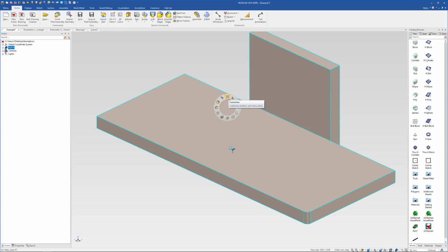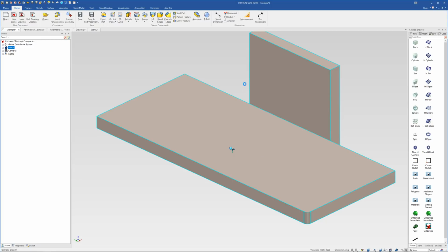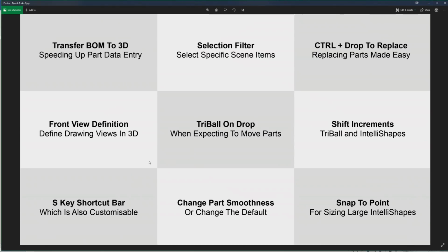When you activate it, this top button here will customize the options. You can select the command state it's in. If you're just in the scene, it'll give you all these options, and you can add new 2D drawing there if you want. If you know you're going straight into 2D drawing, it's often really quick to press the S key, click new 2D drawing, and so on. You can customize those, and you can choose where it shows up, for example at the top of the window like that. It's just worth noting it can be made useful when you customize it to suit your needs.